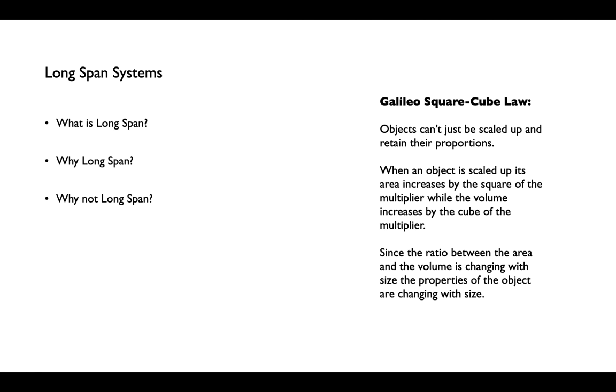Right? When we design beams, for example, that span greater and greater distances, you may recall from our exercises in beam design that we always had this moment where, after we had solved the problem, right, figured out whatever maybe steel beam we need to span a distance, we then had to go back and add the dead weight of that beam into the equation, right? Do the equation over again, see if the beam could carry not just the live load that we were putting on it, but also its own dead weight.